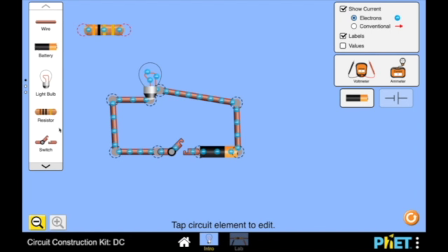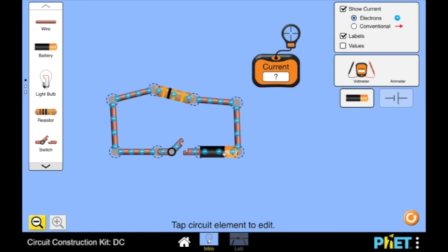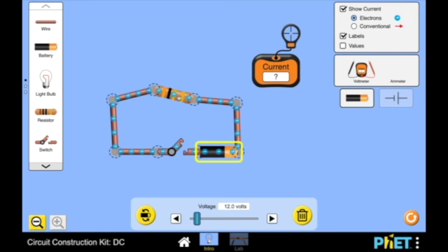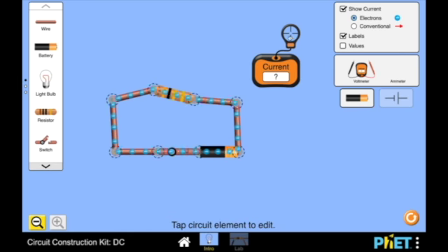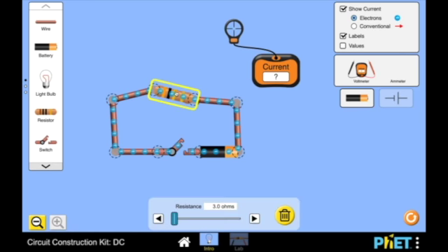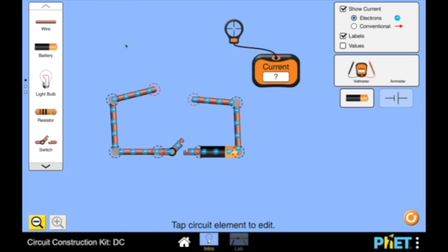One of the other components that I'd love to cover with the class is that of conductivity. So if we take our light bulb here and delete it, and replace it with a resistor, you will see, bring out back our ammeter again. You remember our voltage out of the battery is 12, our resistance here is 3, and so even in this same circuit I should end up with an amperage of 4. But what would happen if we open our circuit and then delete here our resistor?